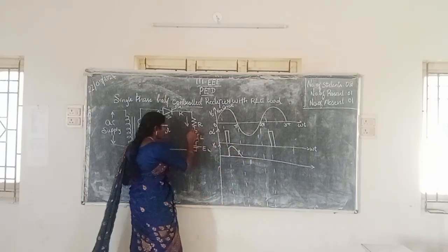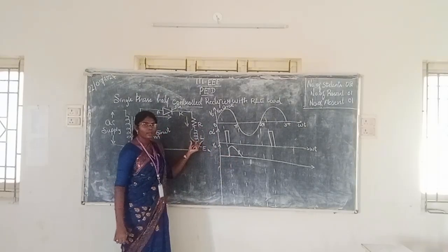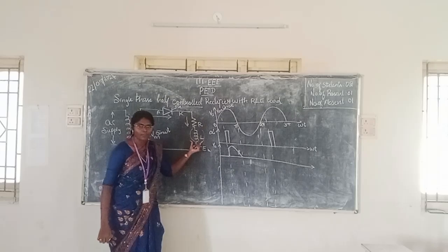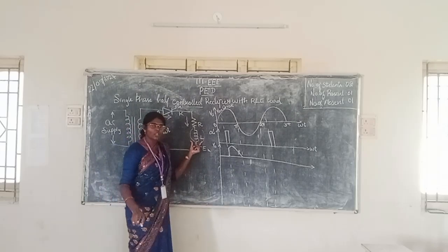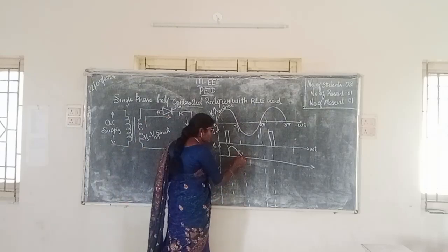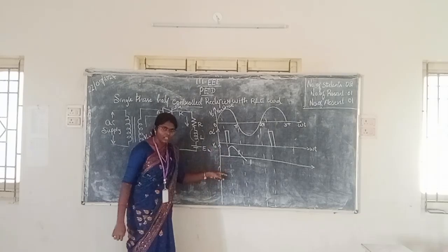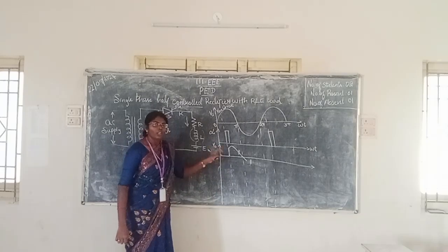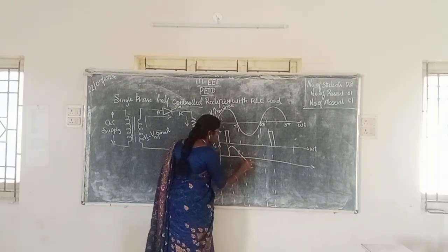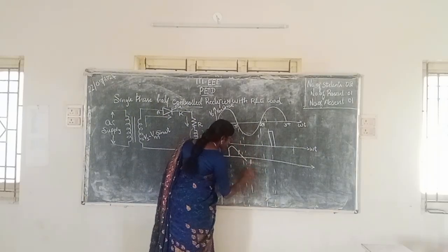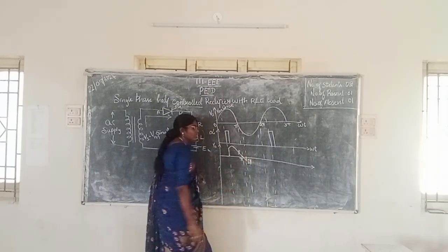Okay, so next, who is present here? This is for resistive load, right? Next to the load, who is here? Inductance. What is the nature of inductance? It will store some current. So due to the storage of current, what will happen? It won't be zero. It will continue until the thyristor shuts down, till it reaches the negative side of the voltage value. So this angle is said to be beta. So this is pi and the second is beta.